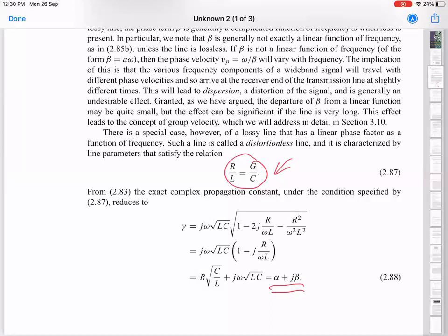There's a side fact that if you have such a lossless line, it will also be a very good thermal conductor, which is incompatible with making sure that the low temperature stage actually remains cold. One of the very important requirements of any low temperature system is that, first of all, you find a way to remove heat from it. That's how you reach the low temperature. And then you prevent all mechanisms of heat coming back into the system. That's why you have a vacuum chamber.